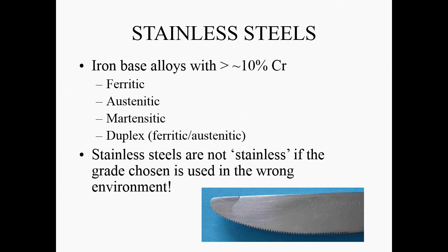So what that tells you is that stainless steel is not stainless if it's chosen in the wrong environment. And chlorides can cause pitting corrosion, and they can also cause stress corrosion damage if you're not careful. Unfortunately, anything offshore, chlorides are very, very common. And in fact, in a lot of onshore applications, these are common. And sometimes people think they can use seawater in heat exchangers, in welded stainless steel constructions, and are surprised when the whole thing perforates in 6 months because of localized corrosion, because they got the wrong steel. So you need to be a bit careful.